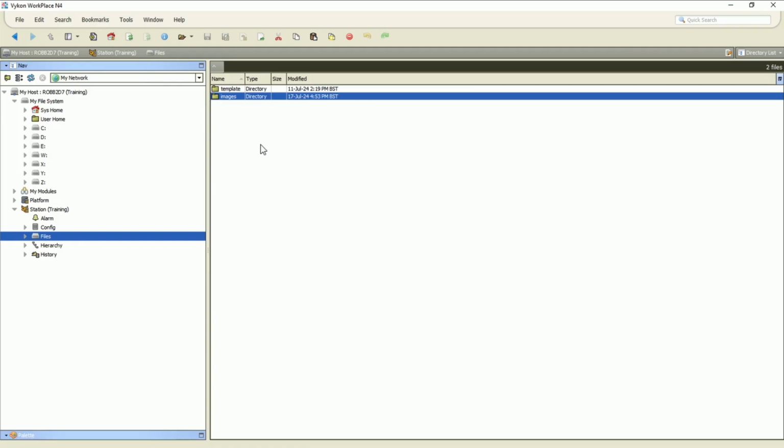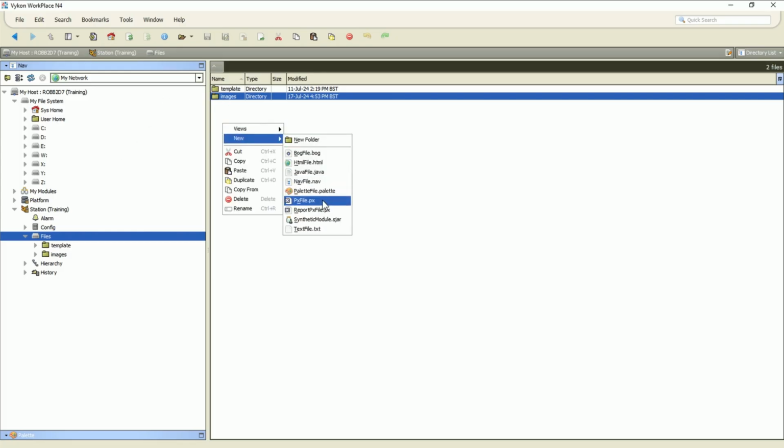So we're going to create several different graphical views across the next few labs. And when we create a graphical view, it will create something that we call a PX file that will live in the file structure. Now we often see that engineers who've been trained in different brands other than Tridium tend to be shown how to do this in a very specific way, in that they'll just dive straight into the file structure, create a PX folder, and then right click and create a new PX file, which is the graphics file, and then they'll just start engineering the PX file and off they go.